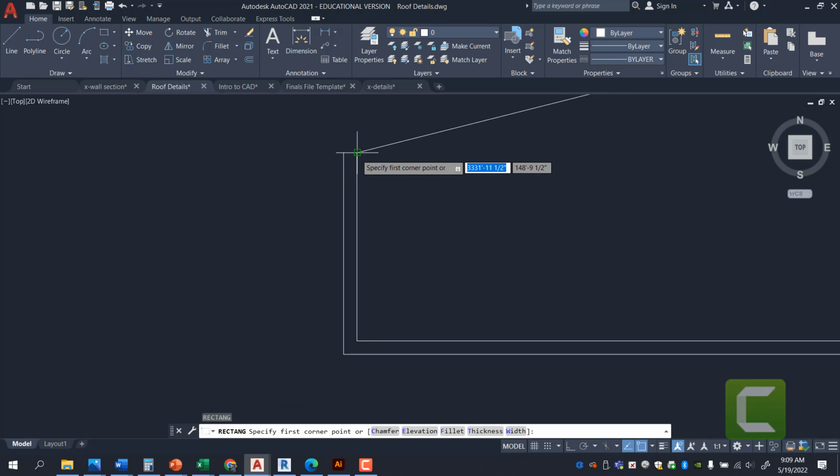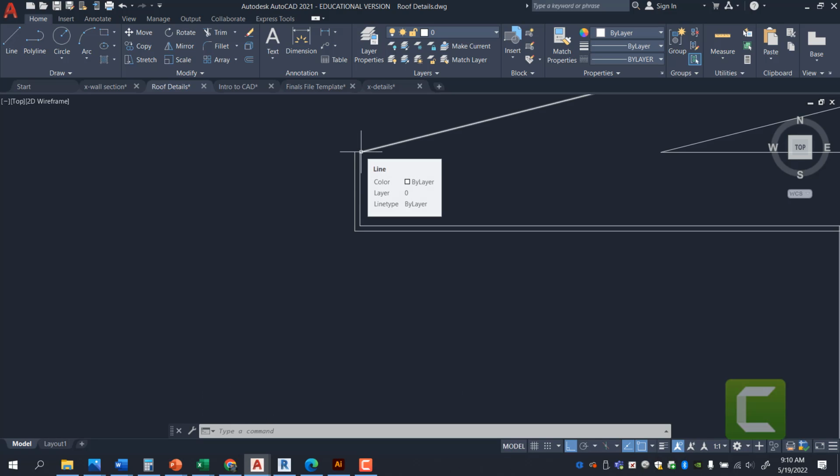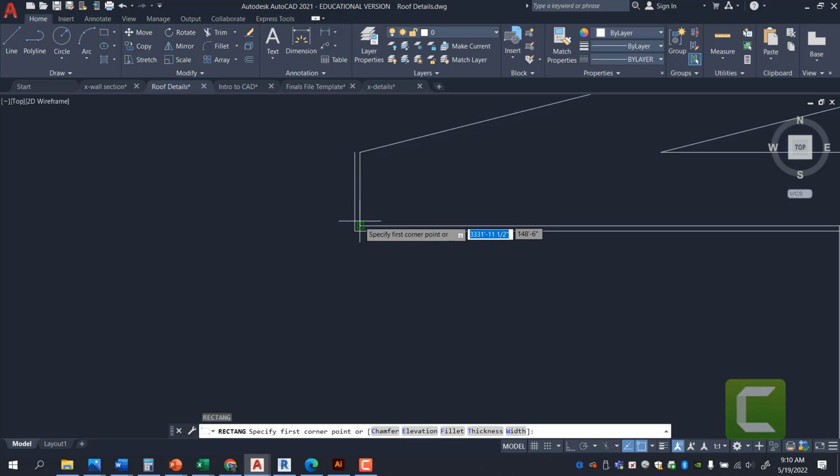And right here, right where you have your fascia, it is common practice now to put in a flush 2x4 or a nailer board. So you have a straight soffit, a straight edge which you can nail your fascia board to. So since we already have a 3.5 inch here, you can nail a 1x4, or what I recommend is a 2x4, which will give you higher rigidity and you have less waviness when it comes to your fascia.